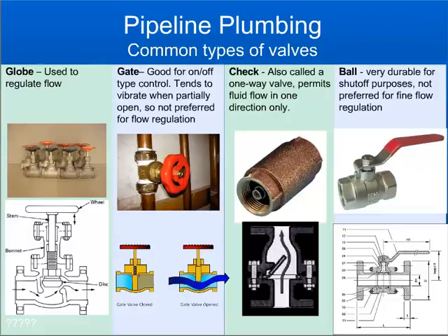The need for valves is very common in all water distribution systems. It's good to have a basic understanding of the different types of valves that are available, and what they're commonly used for. I mentioned in the previous discussion on controlling maximum static pressure for the main line, if you do have a very high static pressure, you might want to put a globe valve right before the tap stand, and so you can see the picture of the globe valve on the left there.